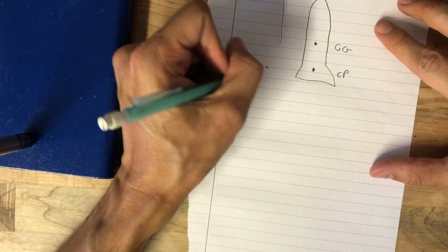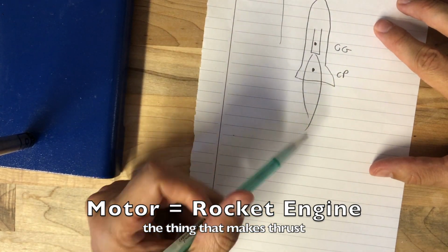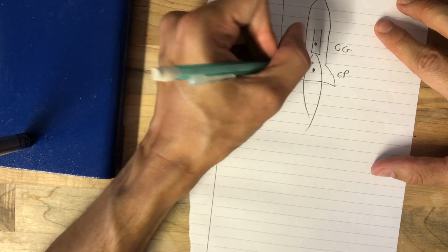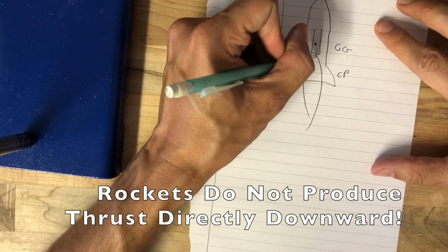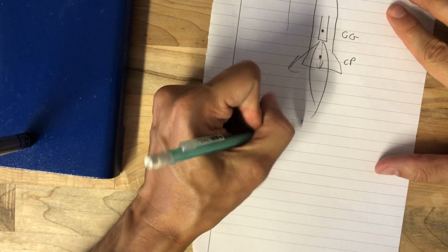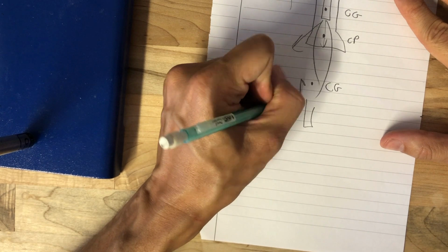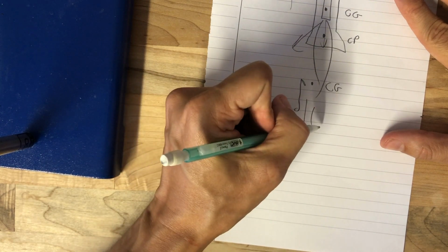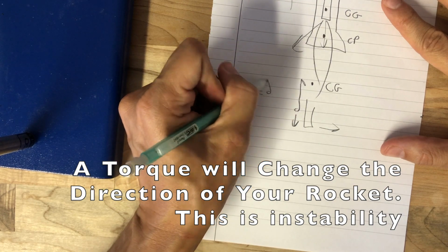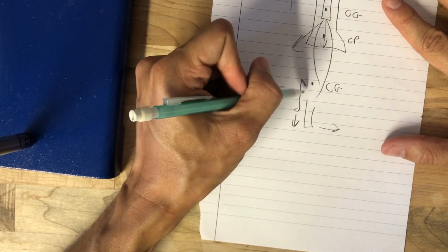So we have a motor in here and it's spewing our ejection so that we have our thrust forward. So imagine that some of this energy is not straight down, some of it's going sideways. Well, the distance between where the motor is and the center of gravity, let's call that D. If we have some force going this way, we have a torque, right? D times whatever force this is.